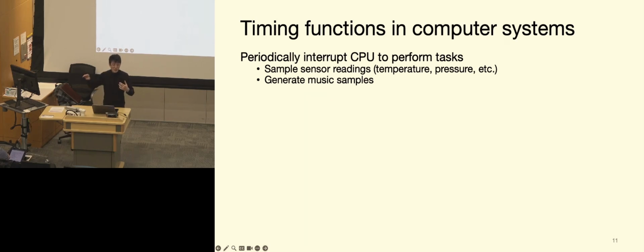If we just did that for one sensor, the whole system would lag, and there would not be much computation power left. So what we do is have the timer work as a periodic interrupt that keeps interrupting at a given time that's been set, and that will give you the reading at that rate. You can decide the frequency of the reading, of course, from the hardware level or software level.